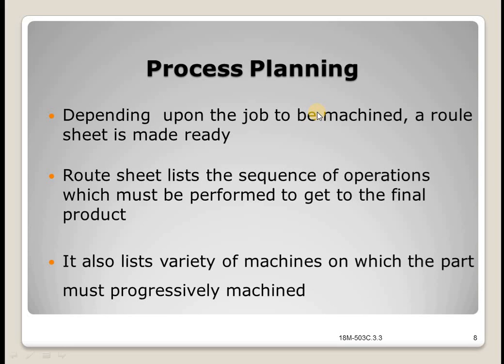So what is a route sheet? A document accounting for the output of production and tracing the sequence of operations of a batch of manufactured components. The route sheet is used in serial and especially individual production to show the workers' output, calculate the wages of the workers and exercise operative supervision of the movement of the work parts in production. The route sheet accompanies the batch of components in all manufacturing operations to aid in supervising the observance of technological discipline and the preservation of all elements.